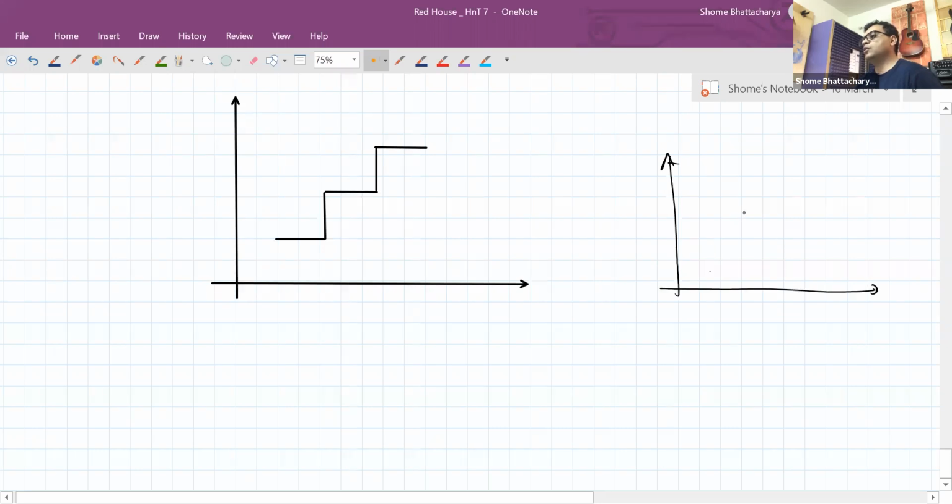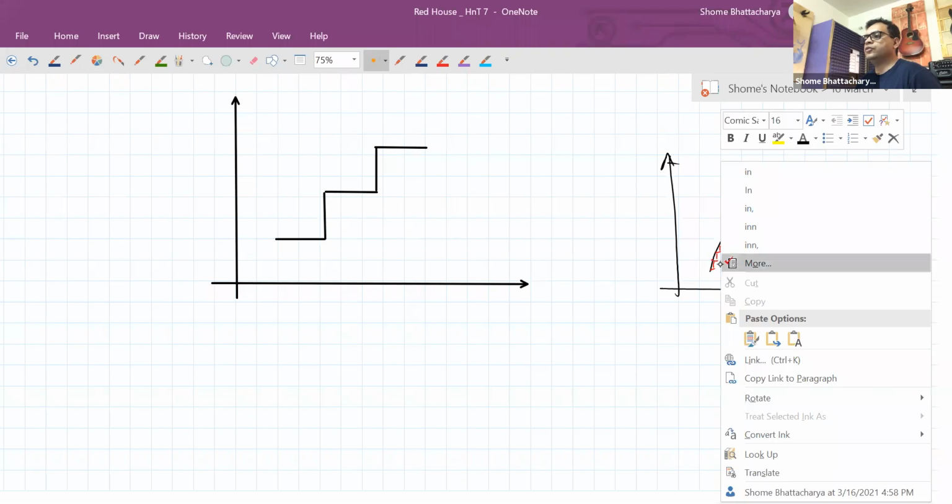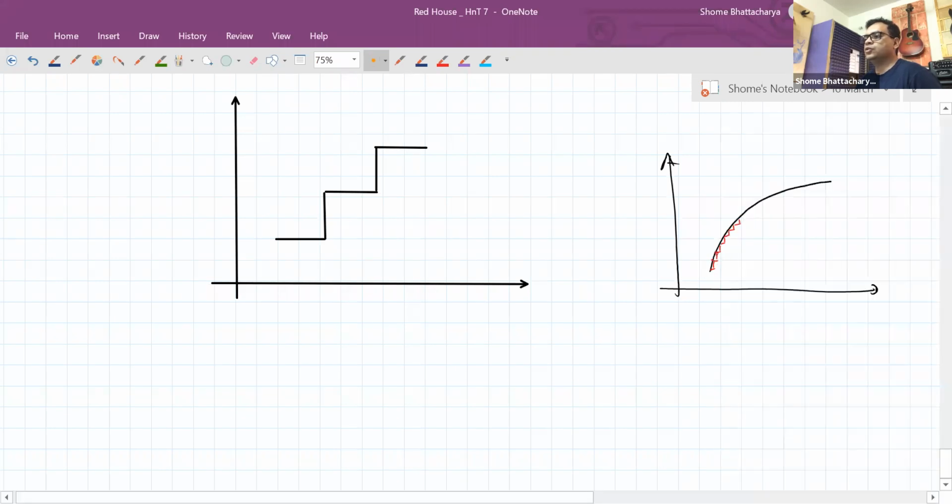So any general path that we want, any arbitrary path, we can achieve it by making small differential changes that we can manipulate. That's why any quasi-static process can also be reversible, because we are going from point to point and each point is in a state of equilibrium. So whatever order we did for these differential changes to create this path in one direction, we can do the reverse of those small changes and the path will simply reverse itself.